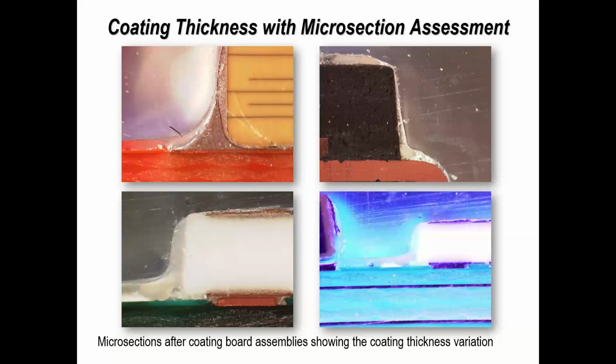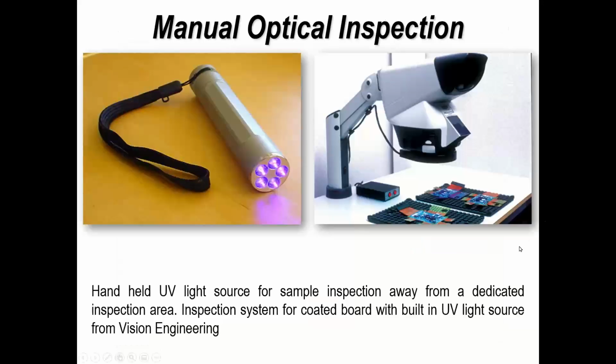So again, if you think about a spray coating, if you're spraying from one side and not both sides, that's one of the reasons that certain surfaces on the terminations may not be coated. So it's up to the engineer who's defining the program for the coating system to overcome that. With dip coating, as you probably appreciate, the material is going to coat everywhere, but then again, you've got to have masking, which is very dependent on the time required for the process.